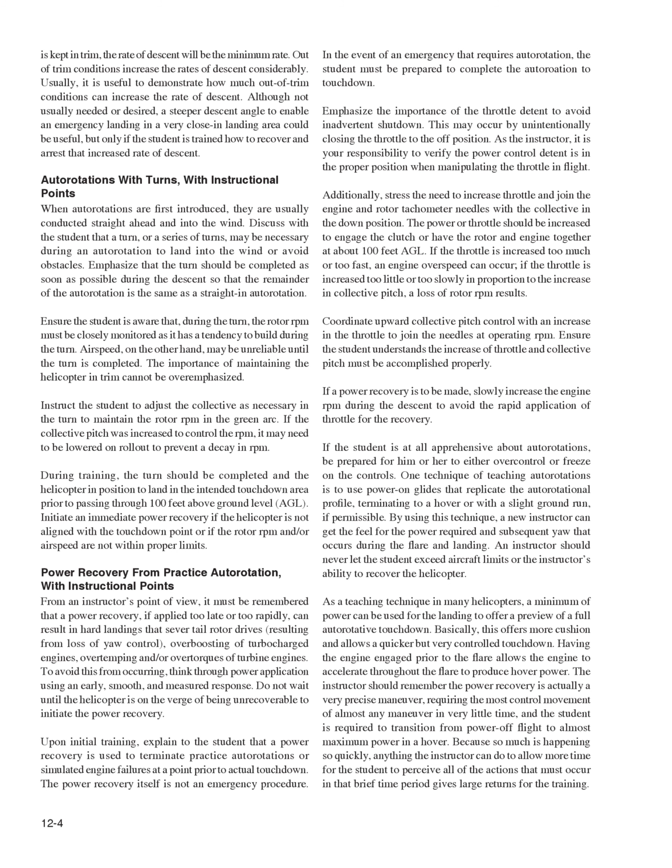To avoid this from occurring, think through power application using an early, smooth, and measured response. Do not wait until the helicopter is on the verge of being unrecoverable to initiate the power recovery.